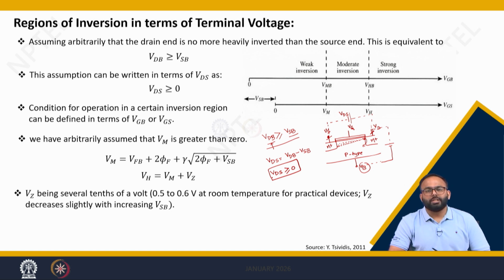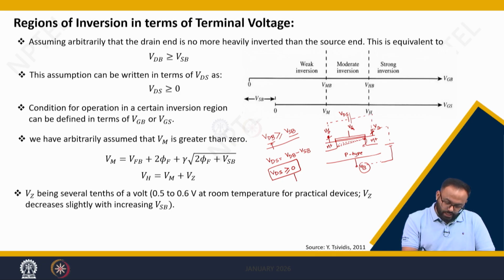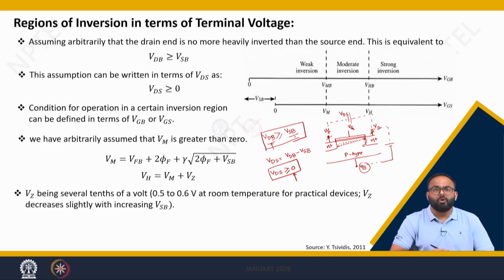In first hand calculation, you have seen that we generally consider VDS greater than 0 in NMOS, right? That is with the source as a reference. However, I can represent all those analyses in terms of VDB greater than VSB, where I am considering body as a reference. So this simple picture helps you understand which reference point you are opting for.